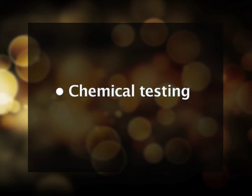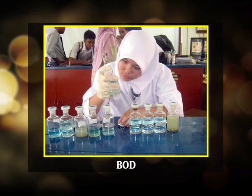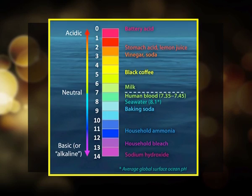Chemical testing. Water samples may be examined using the principles of analytical chemistry. Many published test methods are available for both organic as well as inorganic compounds. Frequently used methods include pH, biochemical oxygen demand, chemical oxygen demand, nutrients, metals, oil and grease, total petroleum hydrocarbons and pesticides.